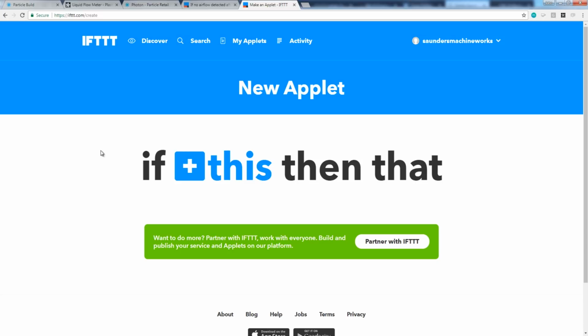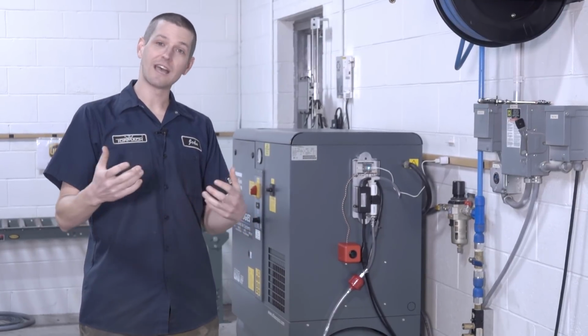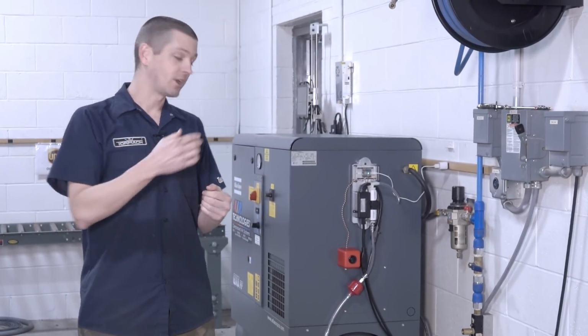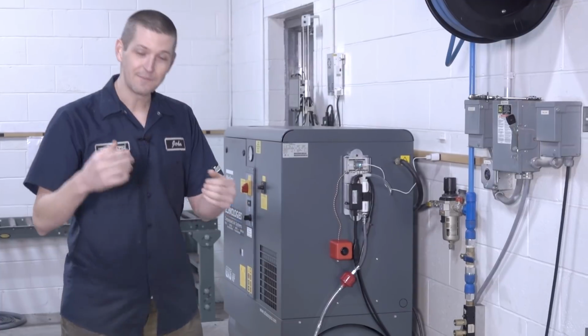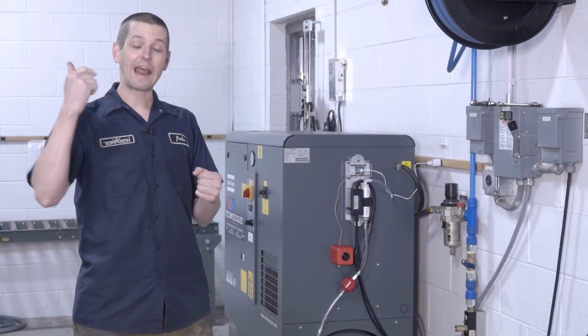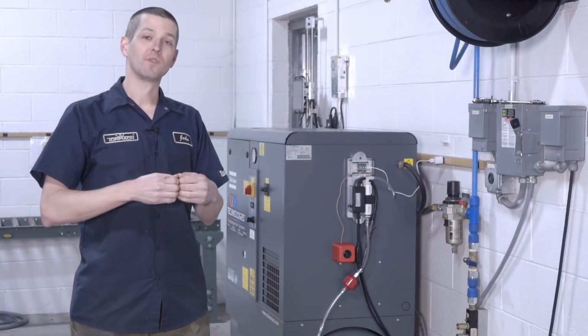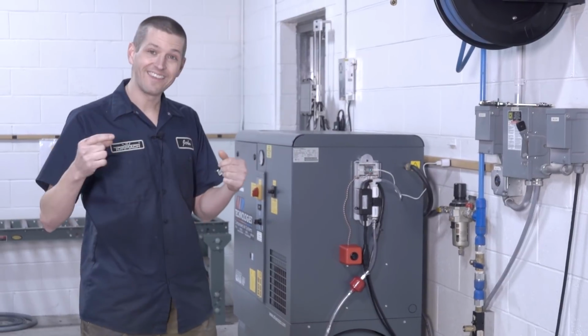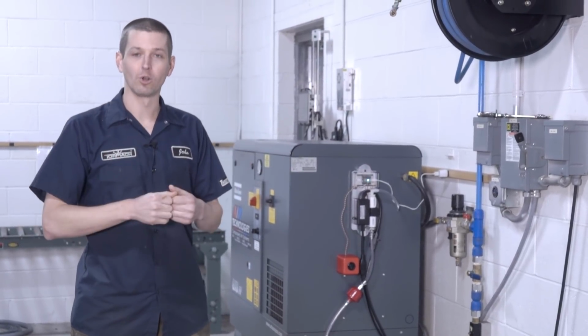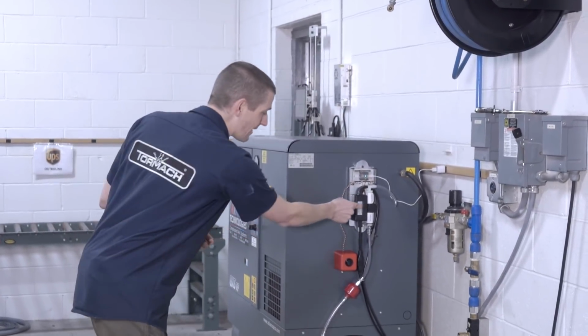We're actually using it for two different things on this project. The first example is the time. So we just have it set up for every hour. So the code looks to see if the shop lights are on and it happens to be on the hour. We could change that interval. Then the Arduino or particle is going to trigger the power tail.